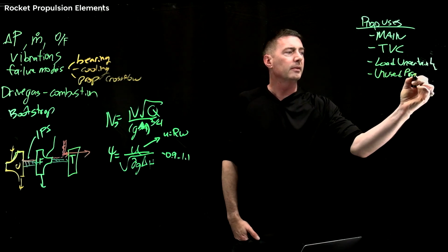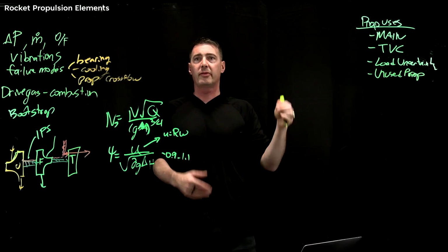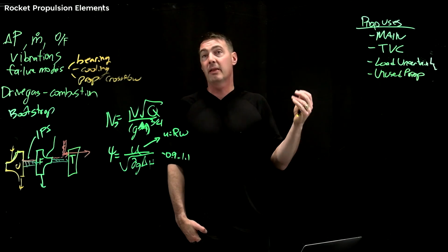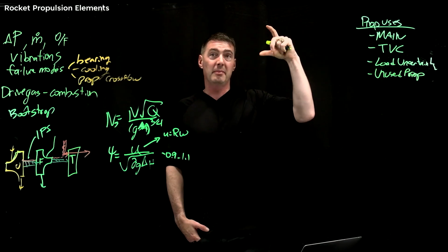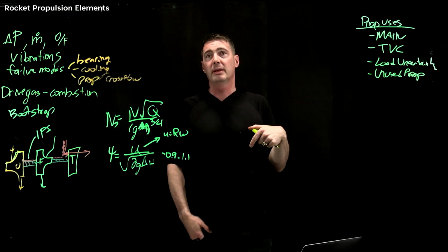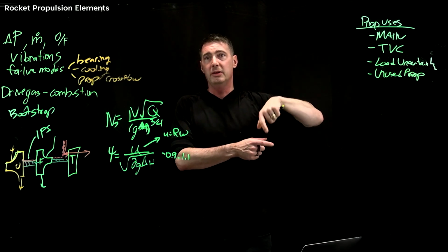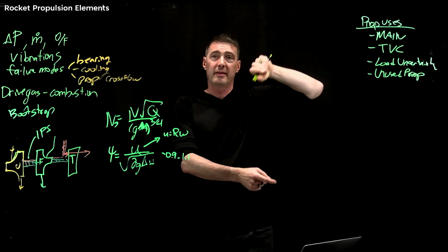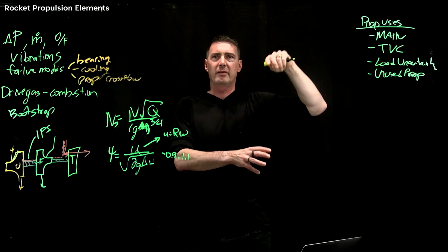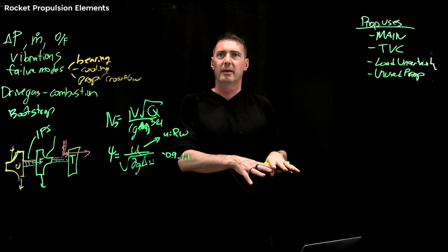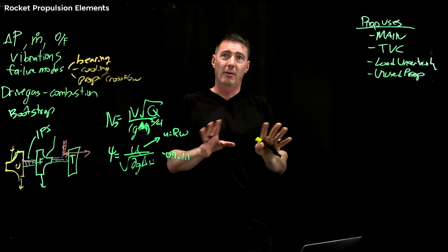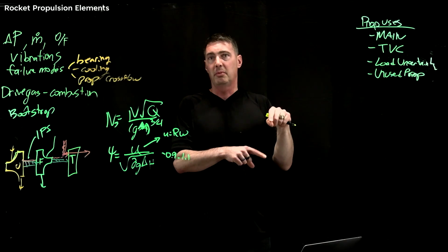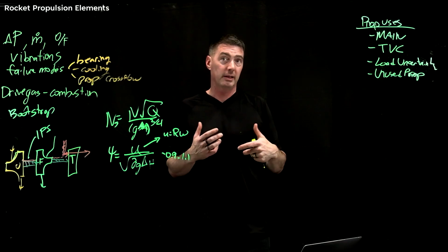So usually within the tanks, you have some sort of liquid measurement system along the way. And you want that to be lightweight so it's not massive. Again, there are really highly accurate but pretty massive systems you can use to measure liquid. Usually what you do is just a small little line in there that's measuring delta P, but there are all of these things you have to do to make sure it's not getting a weird reading. I won't get into more on that. It can be pretty complicated to get your propellant measurement in the rocket while you're going.